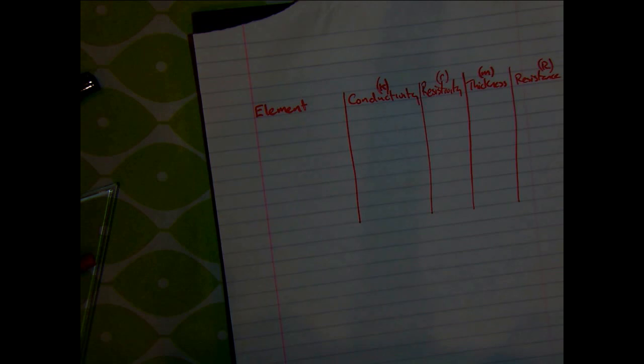Part A of the question is calculate the U value of the wall given the construction that has the following sequence of data. So I'm just going to read out all our materials. So we've external render, concrete block outer leaf, clear cavity, polystyrene insulation, concrete block inner leaf and internal plaster. They all have different thicknesses, you can see them all there in the question. If you look at the thermal data for the external wall, you have the data for all those items, but you also have the resistance of the internal surface and the resistance of the external surface. So please ensure that you include these as well.